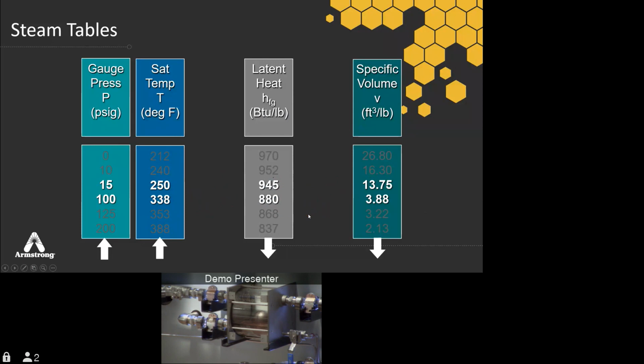And thus, all things being equal, low pressure steam is more efficient than higher pressure steam. If that's true, why do we use the higher pressure steam? Well, two real reasons. The first is that there are some processes that simply require hotter temperatures. And another is sometimes you need more pressure for distribution purposes to get the steam out to the points of use.